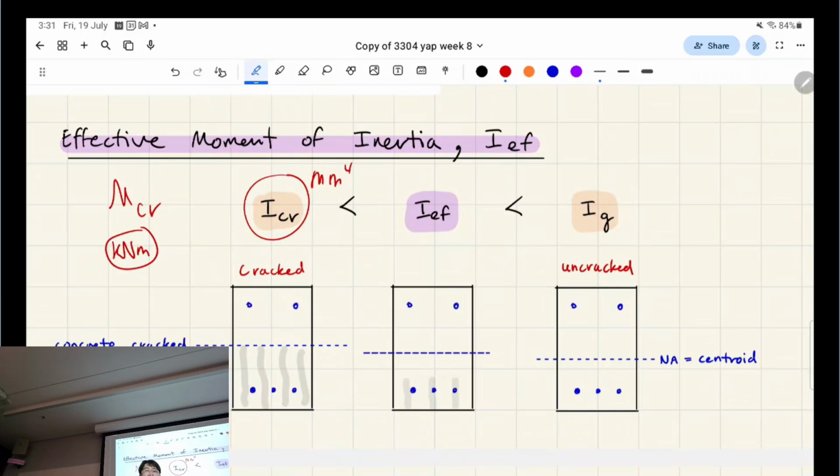So let's not think of external forces. This is more similar to something like area. That bending resistance is a geometric property. In the cracked stage of concrete, you basically assume all of this bottom concrete is cracked, and then you take what that moment of inertia calculation is. So you only consider the top bit of concrete and then the compressive steel and tensile steel. And you use that whole centroid formula for